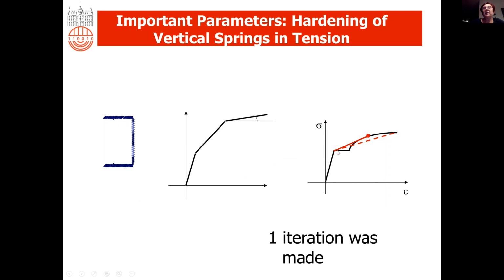In the beginning, we didn't know how much that would be. We first took into account the value corresponding to the maximum deformation in the steel, but later we noticed that the displacements obtained were much lower, so we increased the strain hardening accordingly.